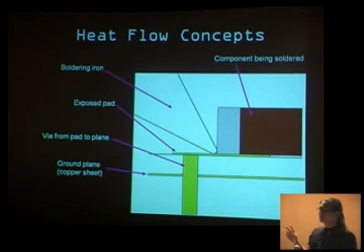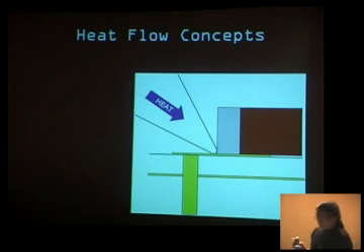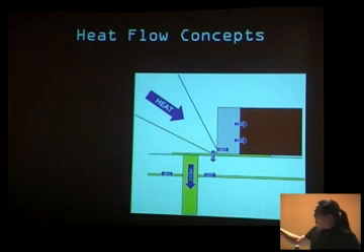This is a common soldering problem that a lot of people don't get when they're first soldering. They won't make this joint right in the first place. The reason is they put the tip down, and the heat comes in. First of all, the heat only really gets into the system through these little points, through conduction. The soldering iron doesn't work by just radiating heat. It actually has to physically touch the component to get heat into it, right? And as the heat escapes from the component, this component is going to heat up quicker because it's got a finite size. But this copper is a great conductor of heat, and the circuit board is sucking the heat out, right?